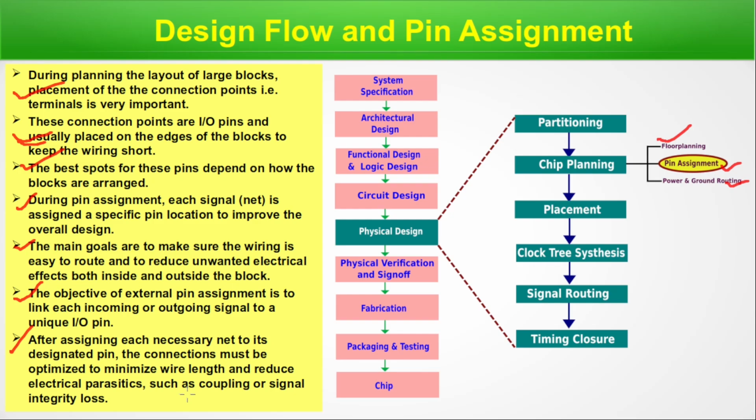In floor planning, we decide where the blocks are situated, what their shapes are, how much area they will cover, and what the aspect ratio should be, as we have discussed in the last episode. With all these blocks, they are not isolated. They have to communicate with the outer world so that we can send a signal and get a response. That is the standard method. So now pins, how they are connected: internal pin to the external pin. In pin assignment, we do that.